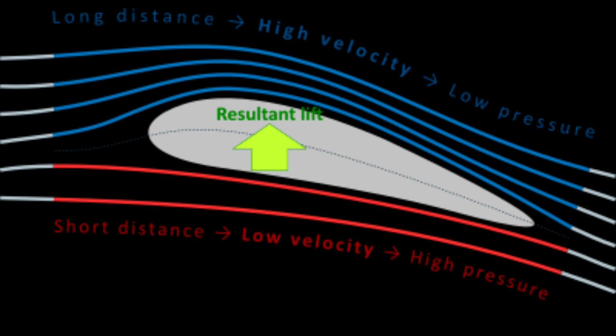A wing moving through air generates the force called lift, also previously discussed. Lift from the wing that is greater than the force of gravity, directed opposite to the direction of gravity, enables an aircraft to fly. Generating this force called lift is based on some important principles, Newton's basic laws of motion, and Bernoulli's principle of differential pressure.